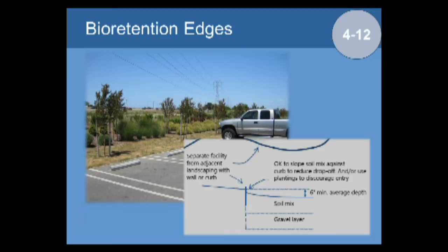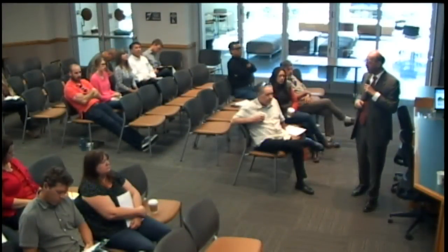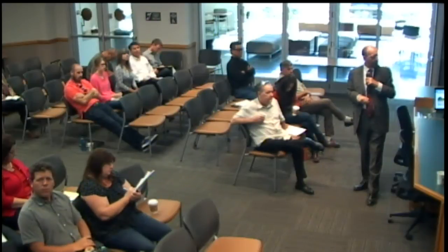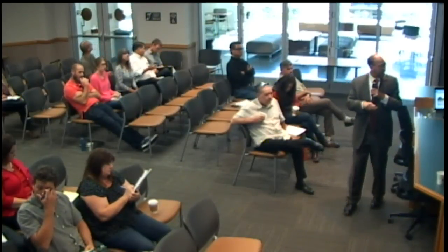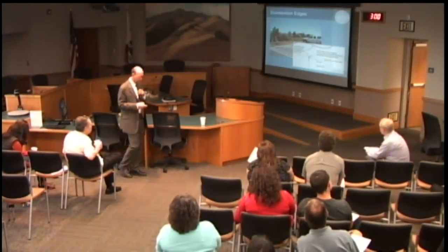This is in the plan view of the bioretention facility. And this just shows that we like to have a clear delineation, something structural that shows where the conventional landscape soil stops and the soil mix of the bioretention facility starts. After all, these are engineered facilities which municipalities are on the hook to ensure are maintained, stay where they are in perpetuity. You would like to have pretty good delineation out there in the field of where they are so you know exactly what you're looking at over time. So simply putting a landscape timber, or even better, a concrete curb in this photo, that would be along this line here. This is conventional landscape and the bioretention facility is out there.